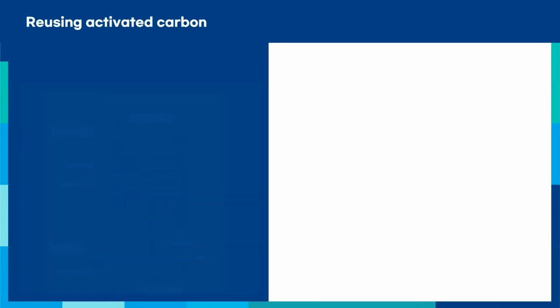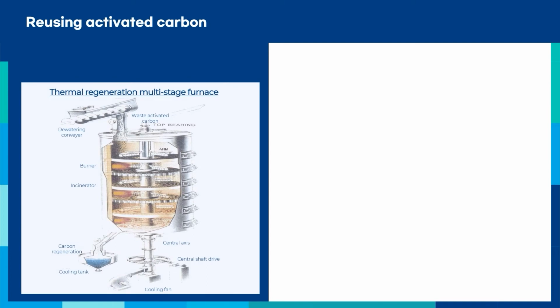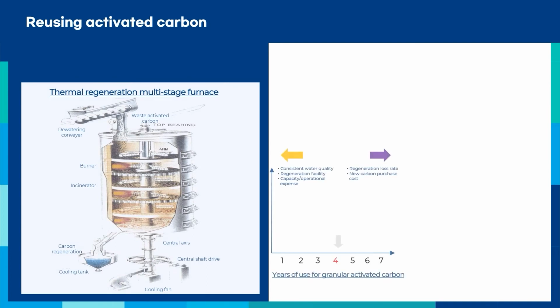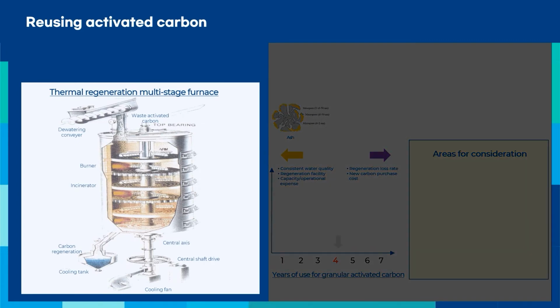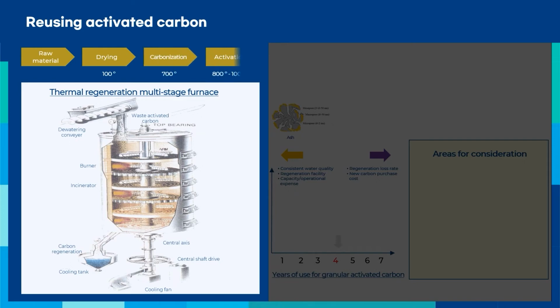When granular activated carbon is used for a certain period of time, the treatment efficiency decreases, and the activated carbon replacement or regeneration process is required. As a regeneration method, the heat regeneration method is mainly used. Activated carbon is economical if regenerated after long-term use, but high-temperature heat must be applied to increase the regenerated quality.